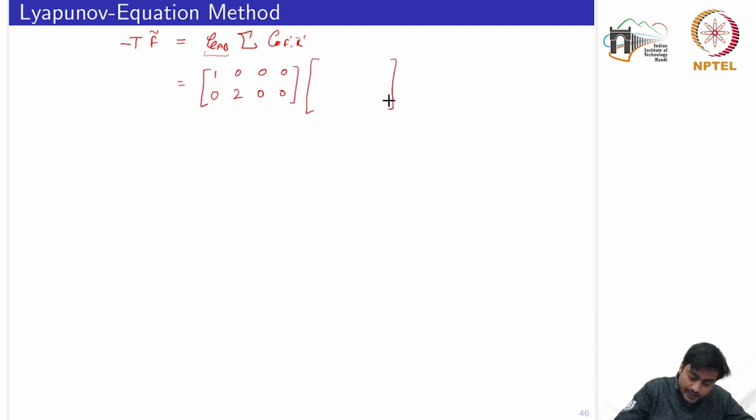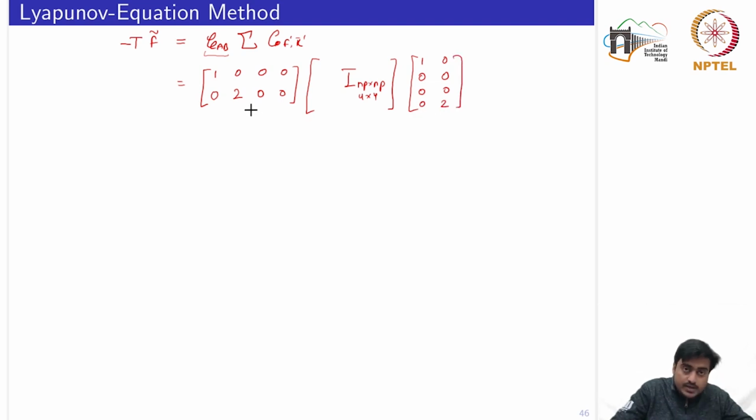We can choose an identity matrix of dimension np times np for sigma, and this controllability matrix of this pair would be of dimension 4 cross 2. Since np is 4, basically this would be 4 times 4, and this we can write as 1 0. So this matrix has full rank, this matrix has full rank, and this is a non-singular matrix.